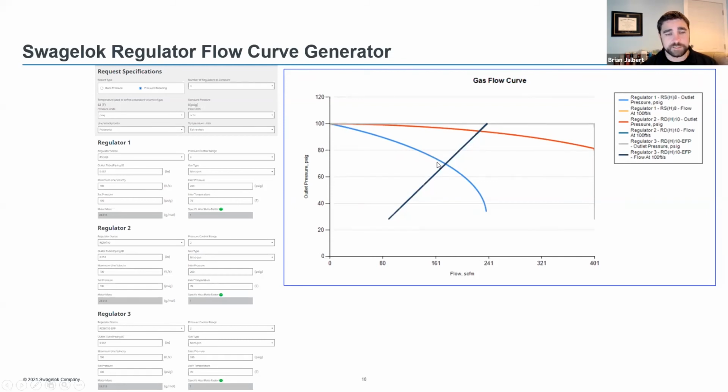That doesn't mean you need to go to a larger regulator. And this is the emphasis I always put on anything with a regulator. The mentality that's always given by calculating flow with a CV rate is I need to go larger. With regulators, you need to go more accurate. All 3 regulators that I have graphed here have the same CV. So this is an RS8 regulator.